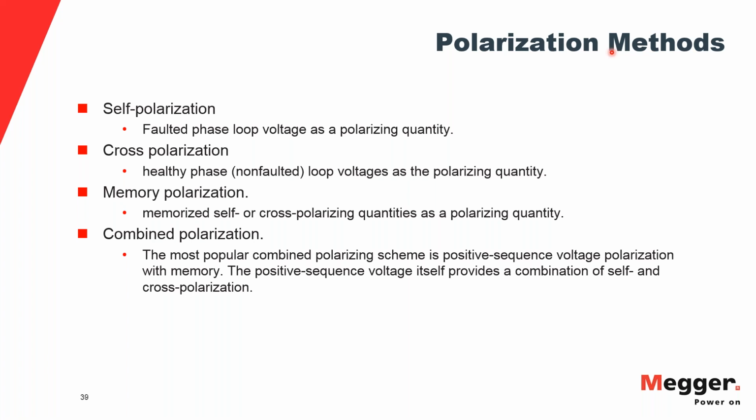Now, the polarization methods used change the behavior of the protection characteristics. The shapes change a little bit. So it's important to know what type of polarization method is used in order to protect the system properly.